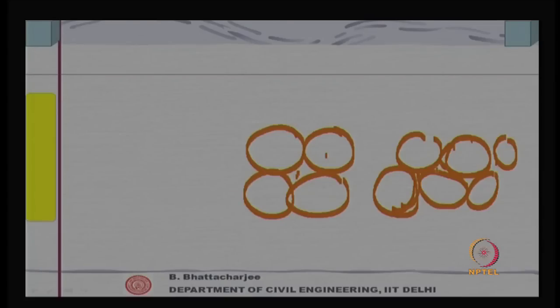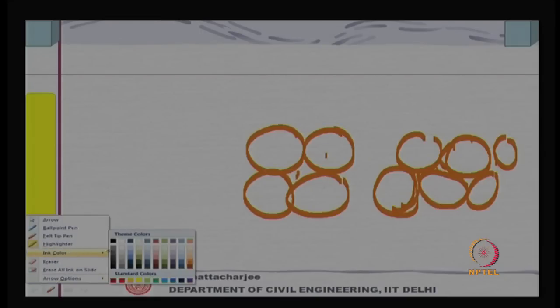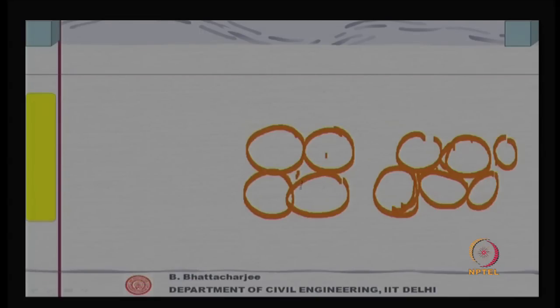For example, this is simple cubic packing, I have larger void compared to this sort of packing, right. So, we have different kind of packings like body centered, face centered, etcetera. We will discuss about them. So, it depends upon packing. Now, if I want to reduce this void, what I shall do is put a small aggregate here and small aggregate here, and small sized aggregate can reduce this void.